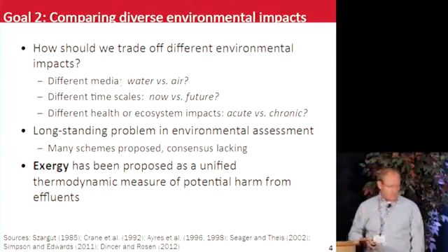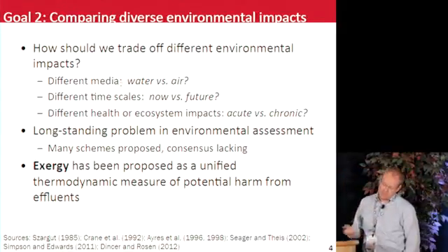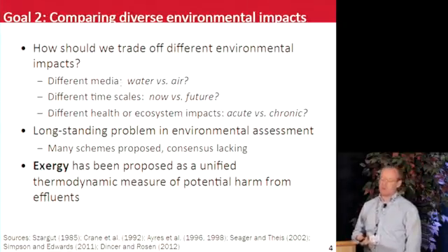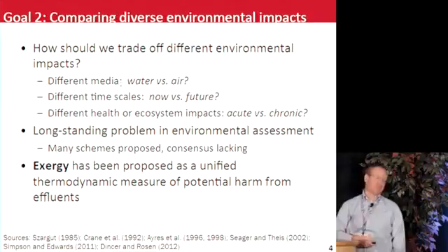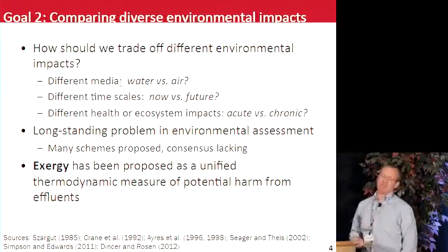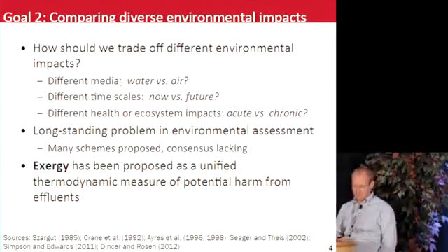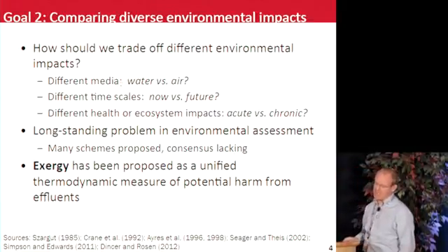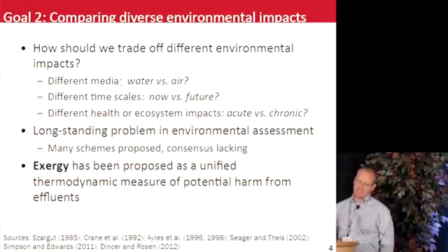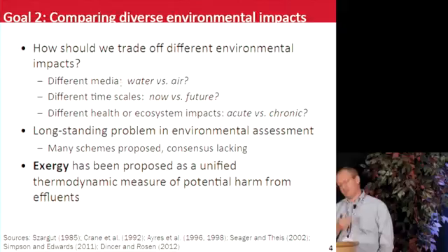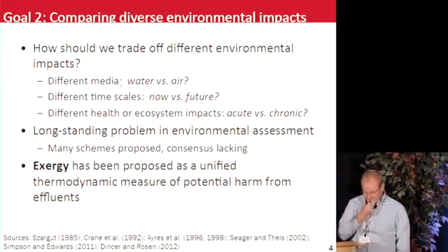We have a project with the Woods Institute, just as an example, in collaboration with a civil engineering professor, where we're looking at co-minimizing energy use and toxic byproduct formation from MEA-based capture systems. As it turns out, monoethanolamine-based capture can release highly carcinogenic nitrosamine compounds into watersheds nearby the power plant, right? And so this is this water versus air sort of trade-off.